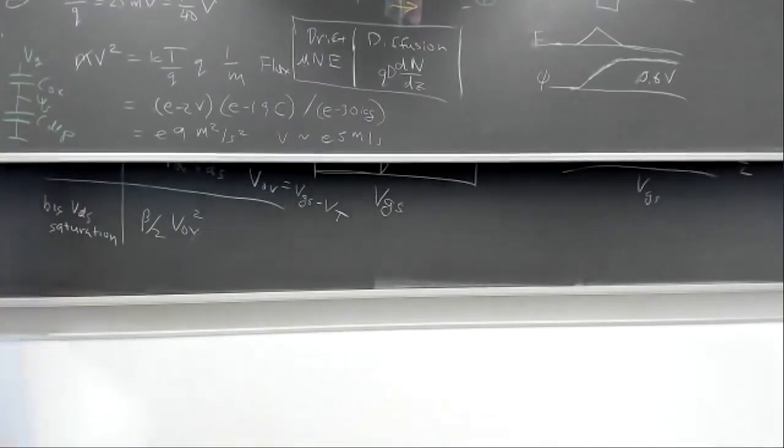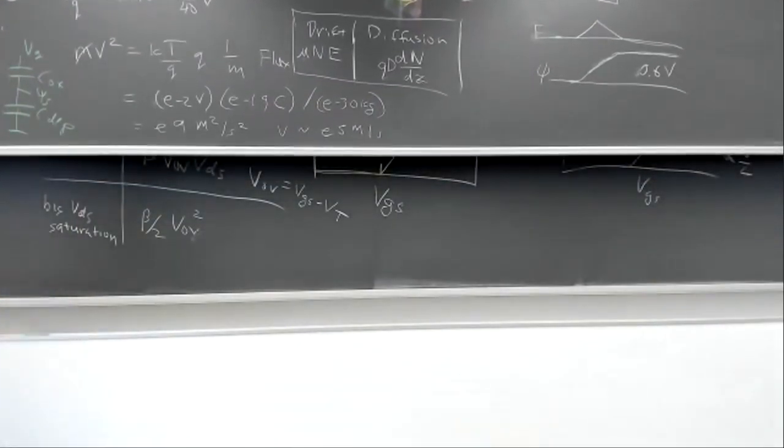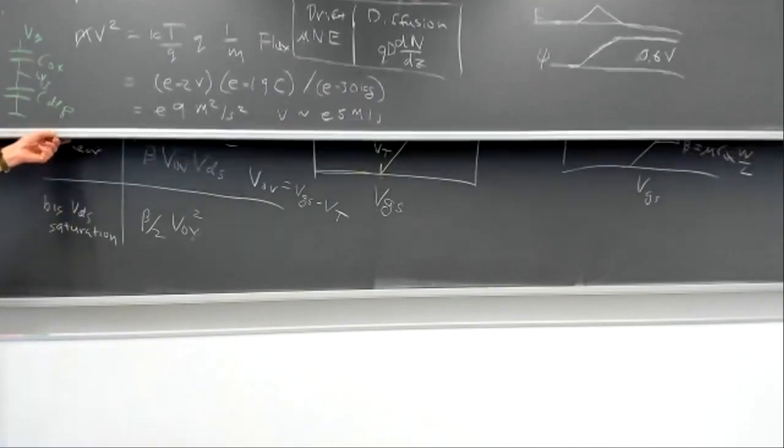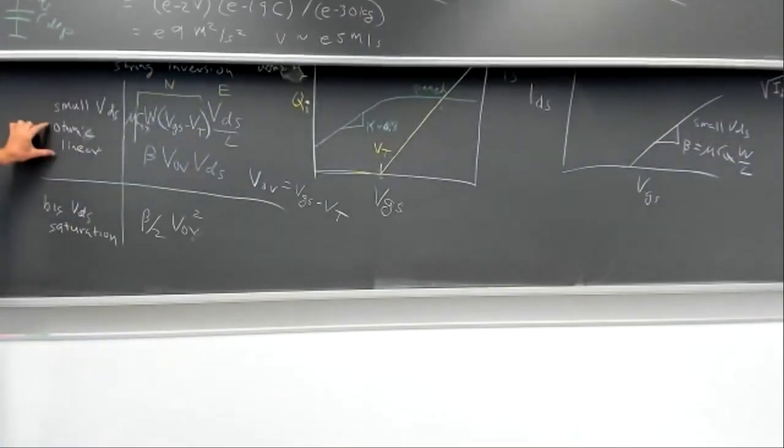So the surface potential is uniform along the channel? Yeah, under these conditions, that's a very good question. Do we assume a constant charge density in the channel? Yes, because there's only a very small electric field across the channel, the charge density is constant. It's just a uniform sheet of charge. Yeah, under these conditions, a small VDS, under the ohmic or linear region.